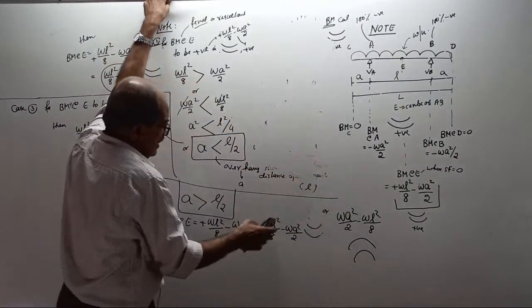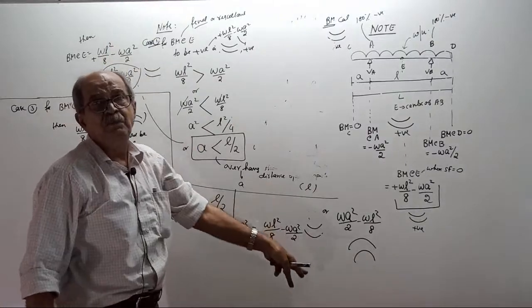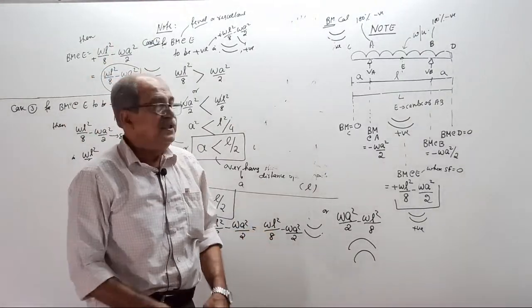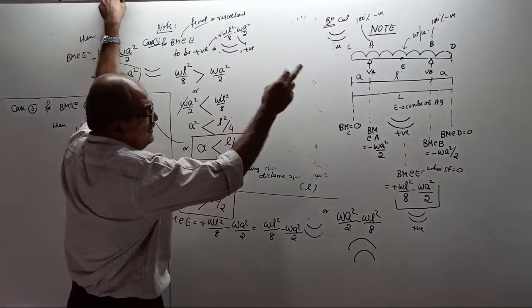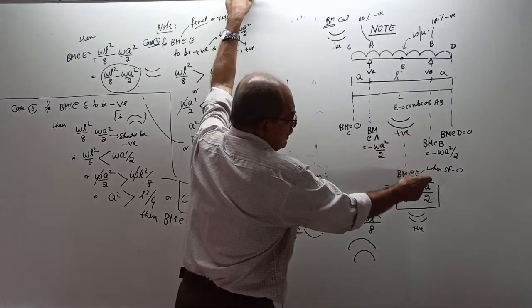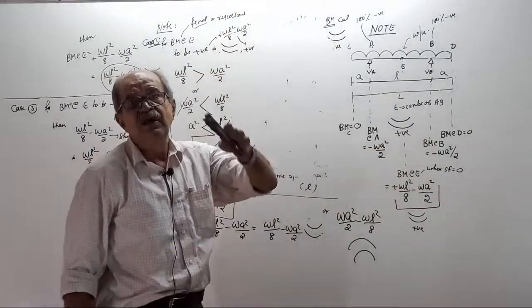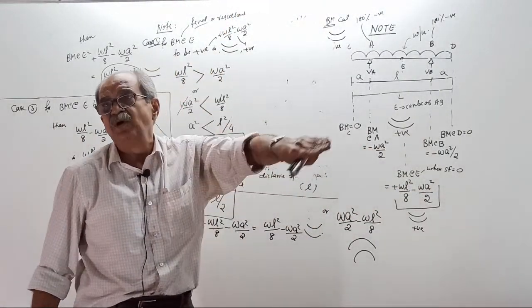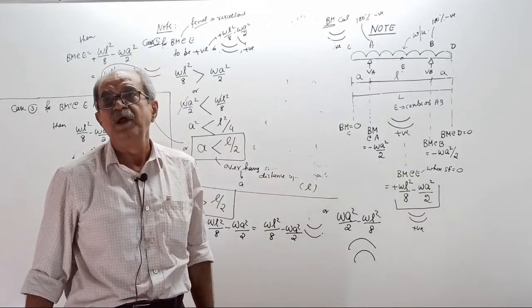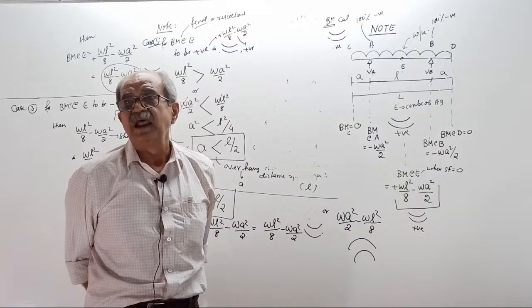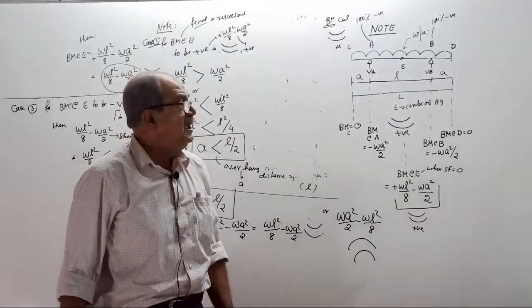Now see, this is called mathematical instinct. If someone asks me, bending moment at E is WL square by 8 minus WA square by 2 based on the sign convention of sagging positive. Okay, agreed. Imagine I go to an interview and that person is trying to trap me. He knows the concept.